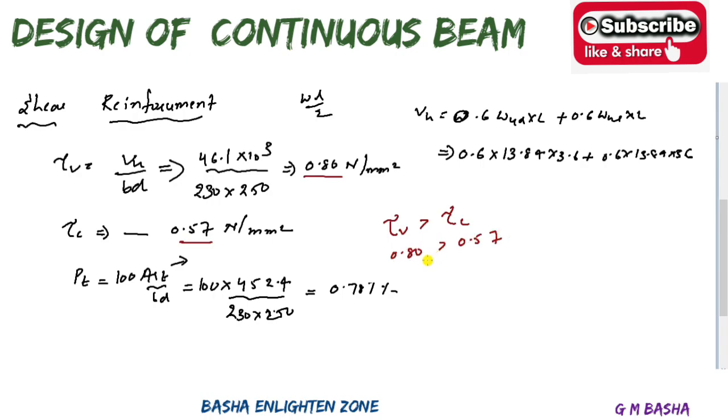You please remember one more thing here. The tau v range will be after calculation of the percentage of steel. So it will lie between 0.75 to 1. So the range will be 0.56 to 0.62. If you observe clearly, your tau v will be some 0.61, and we don't know tau c at that time. If you calculate you will get 0.662, we will get confused, but already tau v value will be higher. Already if you take 0.62 also, it will be higher.